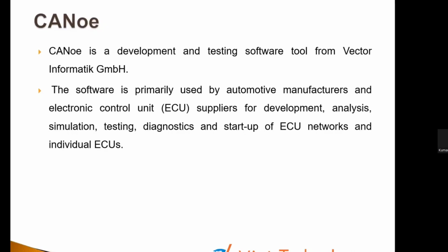What you need to do is create some CAPL scripts inside CANoe where you send the speedometer readings, odometer readings, trip readings, petrol readings and temperature readings, whatever is available in the cluster. All these messages can be sent 1 million times, or as the specification from the OEMs says.